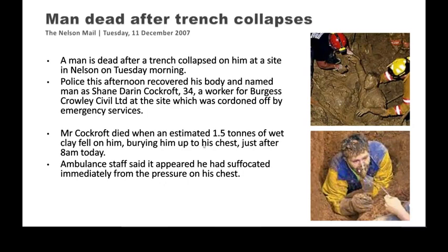So 1.5 tons, there's no way anyone can actually deal with that weight on top of them, and it's just going to knock all the air out of your chest straight away. And then no one can dig you out quick enough. You've only got a couple of minutes to rescue someone, and that's just impossible. Even if you got the head free, which you probably wouldn't do in a short time, if their chest is compressed, they can't breathe anyway.